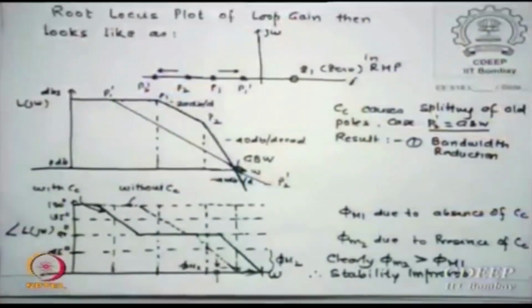If you use that CGD, your phase margin will be close to 45 and then you will have a problem. So you want phase margin to be at least 55 or something, and that is my worry. So let us look at the loop gain Bode plots.